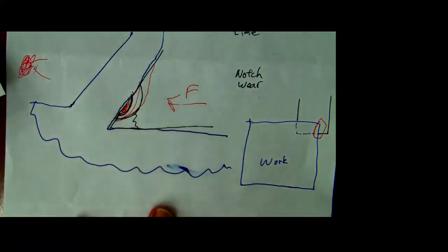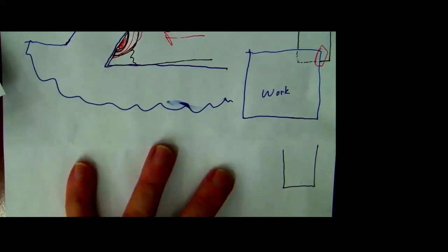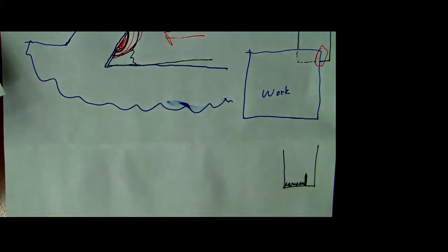So it's not uncommon for me to get wear that would look like, whoops, I'm down off the bottom. Let me move it up. I get wear, if it's going to wear, it's going to wear like this, like this, like this, like that, right? Okay? The part on the right isn't going to wear because it's not cutting anything. The part in the center, or on the left, is cutting uniformly and nice, good material. The part that's cutting where the edge is may get a notch.